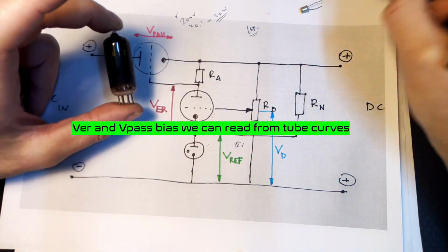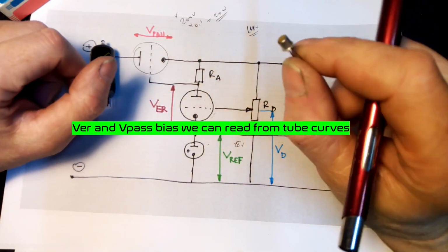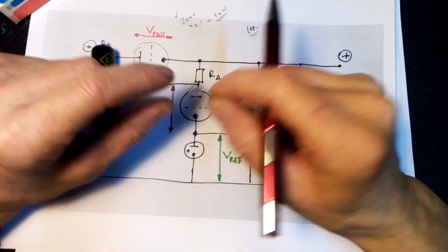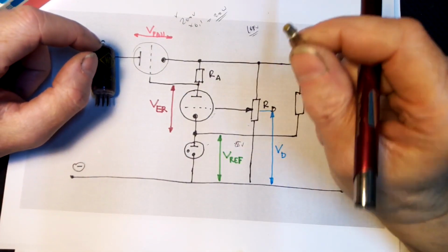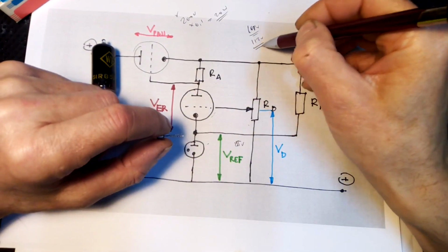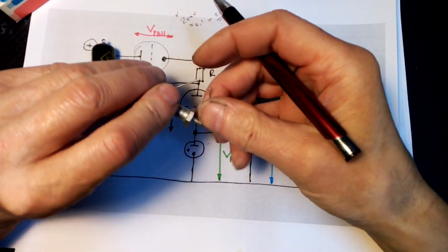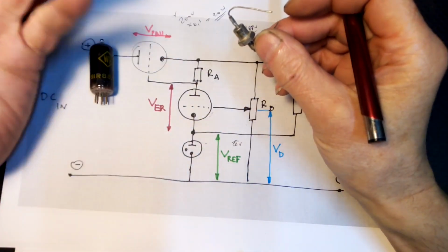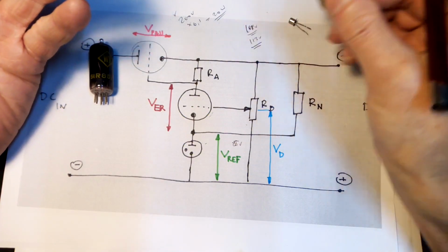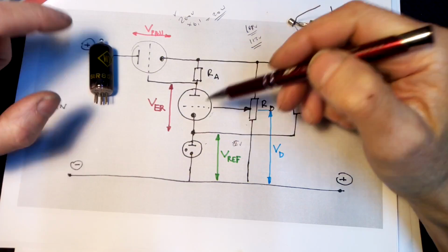Of course, if we use such a small device, this is 33 volts, so let's say we can go even up to 115 volts in this case. And the same concern applies to the Zener diode. This is 43, but of course we can find one for 33 volts also. So this is one thing we have to remember.